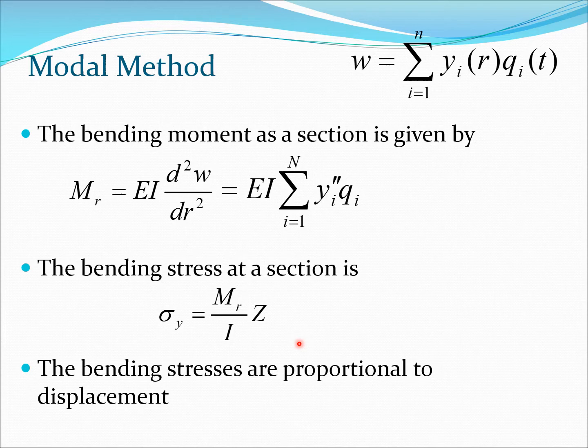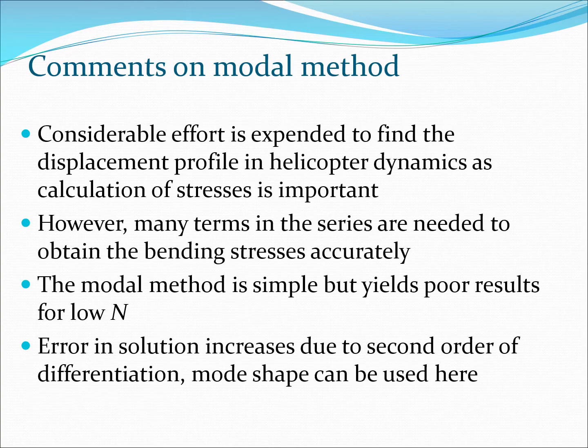Now the bending stresses are proportional to displacement. So you can clearly see here that the bending stresses would be proportional to displacement. Now this method which we discussed is known as the modal method, and it is often used in many helicopter codes to calculate the bending stresses.